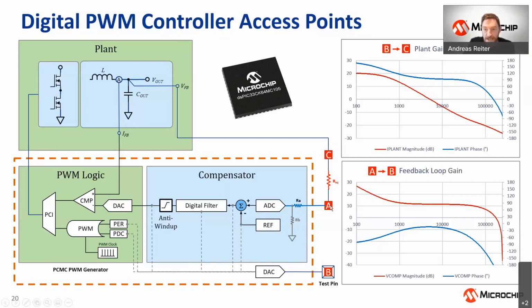So an error signal that would be injected, let's say, in the common way by just using the injection transformer, and you're applying this error signal to your feedback network, the resolution with which the error will be seen and received by the compensator is actually 12-bit. And so the response is then, in this case, also given with the same 12-bit resolution.